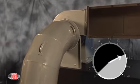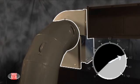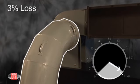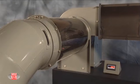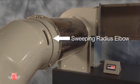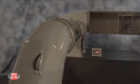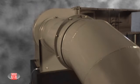Changing the inlet box to an elbow will help. Properly installed, a sweeping radius elbow can result in only a 3% loss of airflow. A good rule of thumb is that elbows near the fan's inlet should be radiused and include turning vanes when located within 3 duct diameters upstream of the fan, recognizing that mitered elbows with or without turning vanes can cause system effect even when located up to 5 duct diameters upstream.